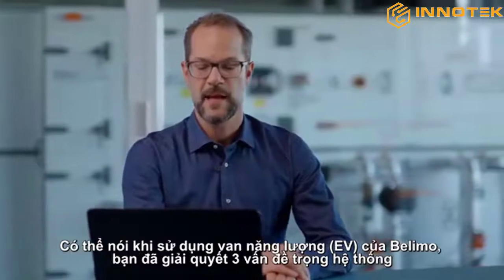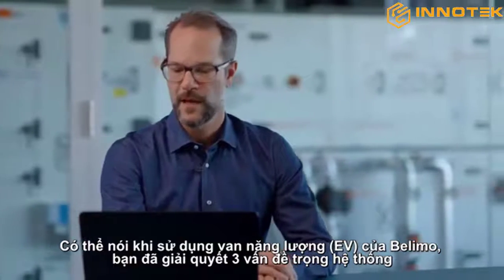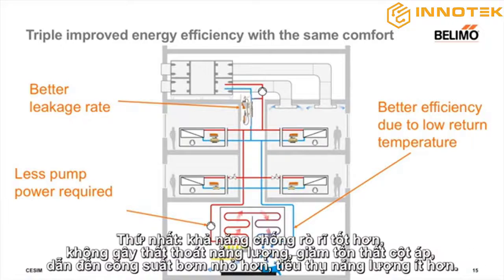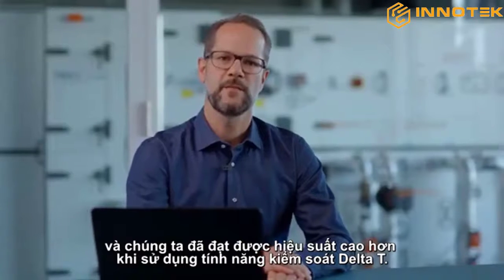In summary, it can be said that with the Belimo Energy Valve, you can achieve a triple improvement in energy efficiency with the same comfort. Only with this one valve, it is possible to have an influence at 3 points in a building. A better leakage rate reduces the energy flow, reducing the differential pressure leads to less pump power, and we achieve higher efficiency at the boiler through DeltaT management.